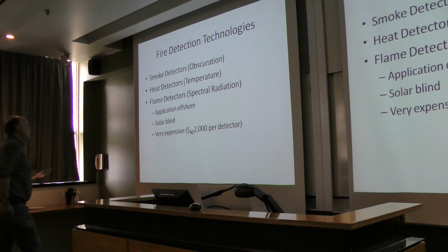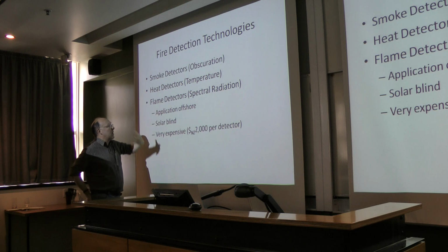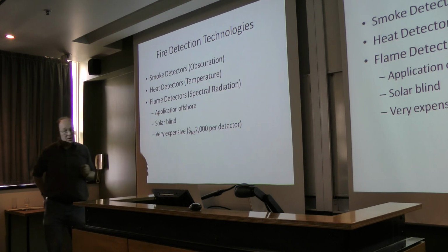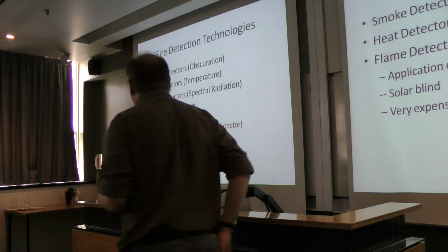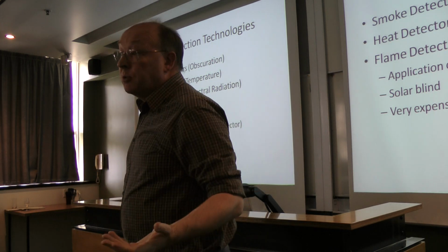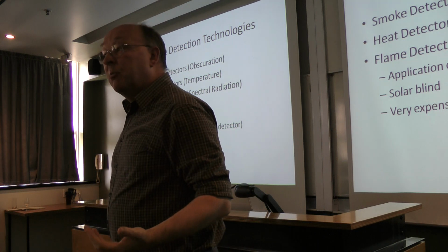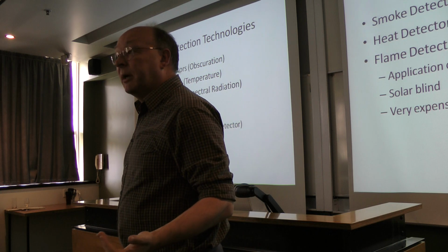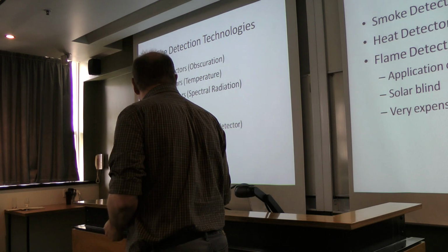And obviously, it's radiative heat transfer I'm interested in, so it's sort of like a heat detector. But it's more like a flame detector than a heat detector, in my opinion, because it has a fast response. Heat detectors are quite slow. The other thing is they don't use heat detectors offshore because of the speed. They don't use smoke detectors offshore because most of the time they haven't got a ceiling, so they haven't got anywhere for the smoke to accumulate. They don't know where to put the smoke detectors if they were to use them. Okay.